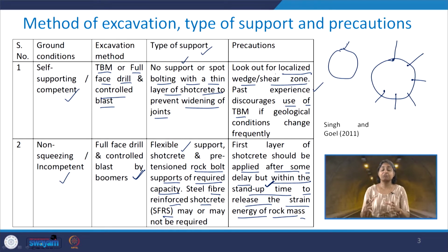If the ground condition is self-supporting or competent, you will have a very large stand up time. That means the rock mass even after excavation can stand on its own up to that much time. This time is called the stand up time.